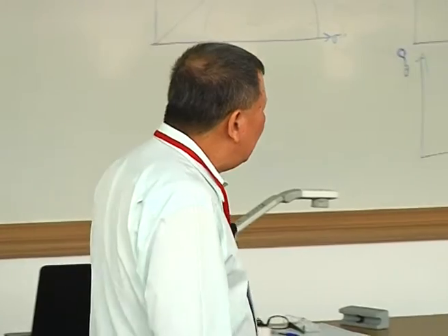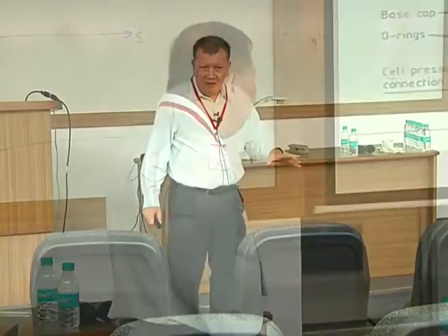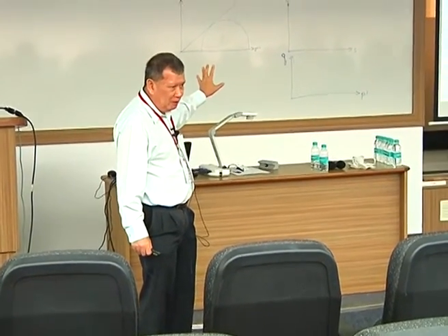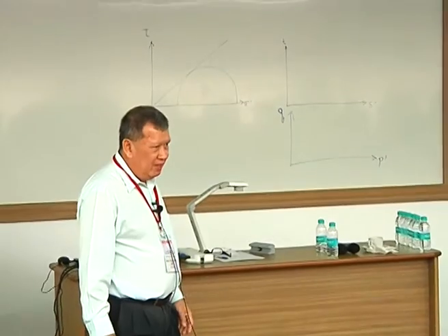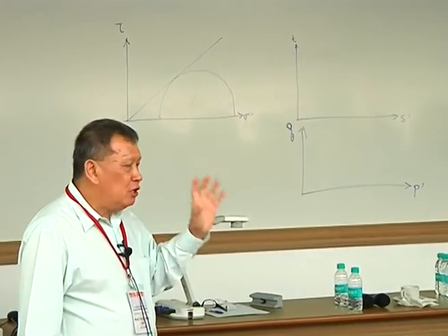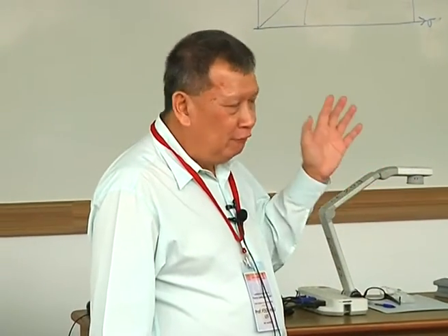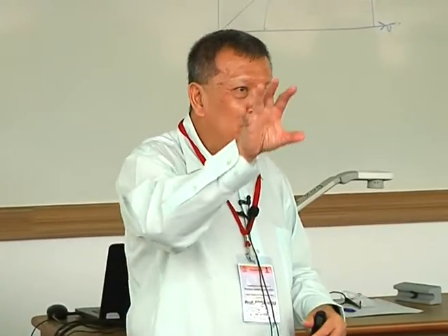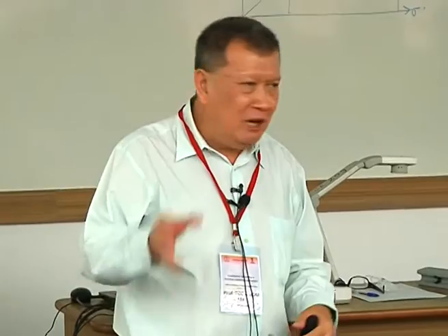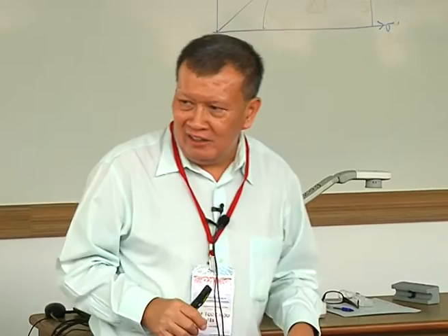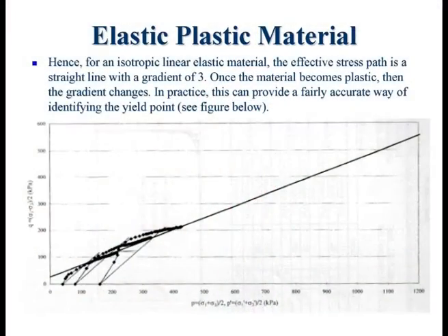Okay? So basically, triaxial condition. Now, this is a very important thing. The important thing I want to emphasize is to keep your thinking simple with respect to stress path parameters. The x-axis is always the good guy, and it always has something to do with a measure of effective stress. The y-axis is always the bad guy, and it's a measure of the shear stress. That's all there is. How you weight it, what component you consider, what you don't, that's a different thing, but the intent is the same.